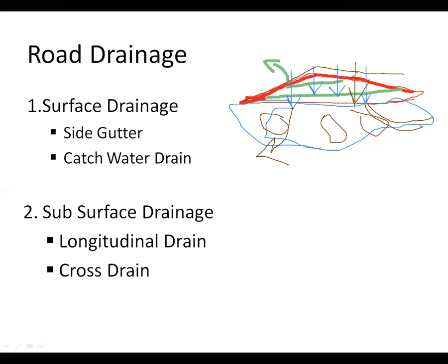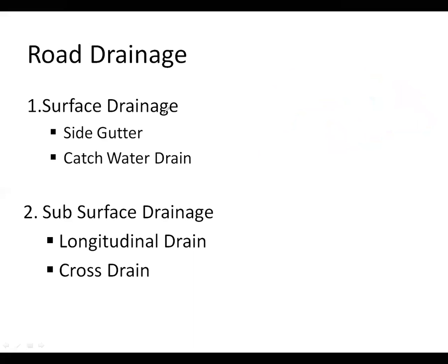That's why we prevent water from being stored or staying on the surface. For that we provide an impervious surface, and we provide camber and many more things, so that water will not percolate into the subgrade.